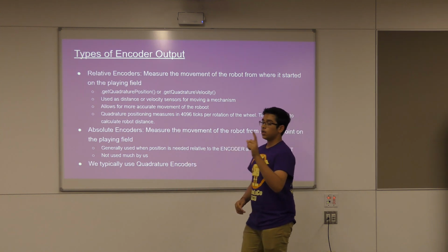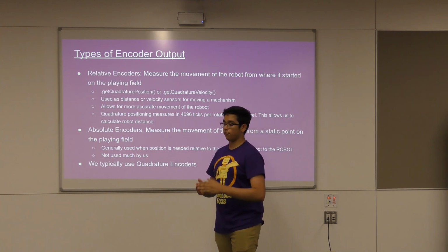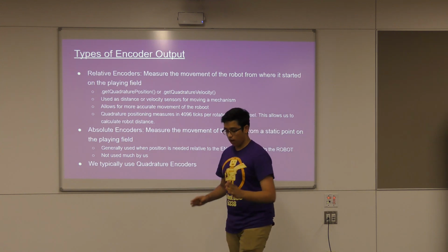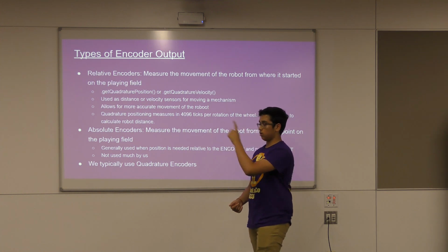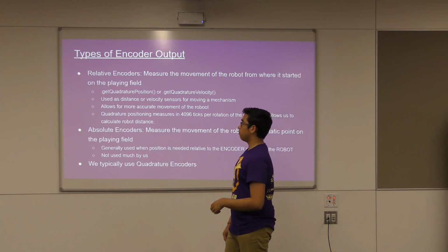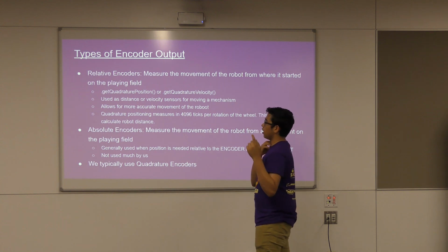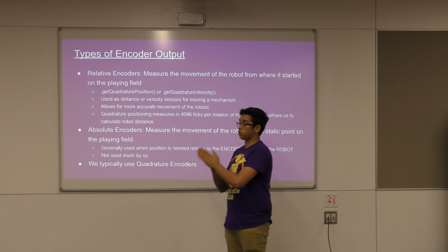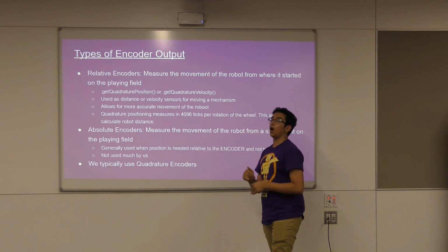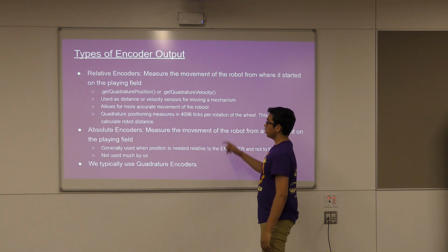But same thing with the turning. What happens if I just use the encoders? I say stop the motor when I get to this many ticks. It'll overshoot. So same algorithm, which we'll talk about Saturday, it'll tell you how much before the target I have to slow down so that I stop at the target. So that's the other encoder.